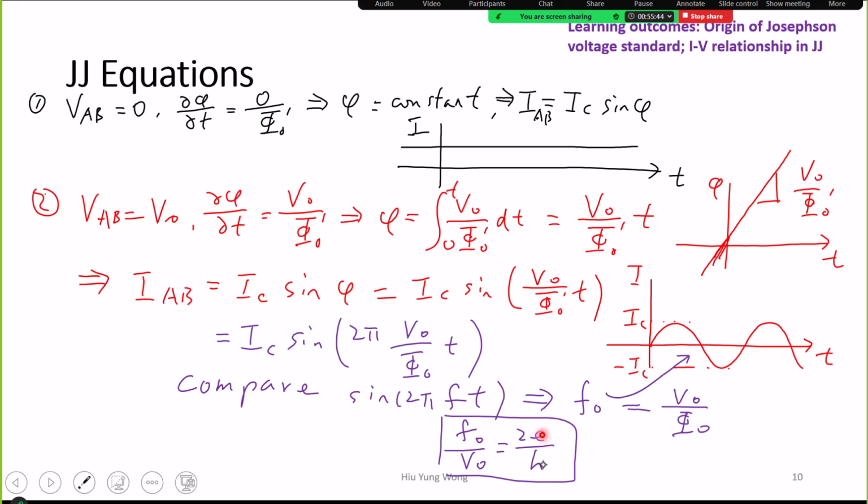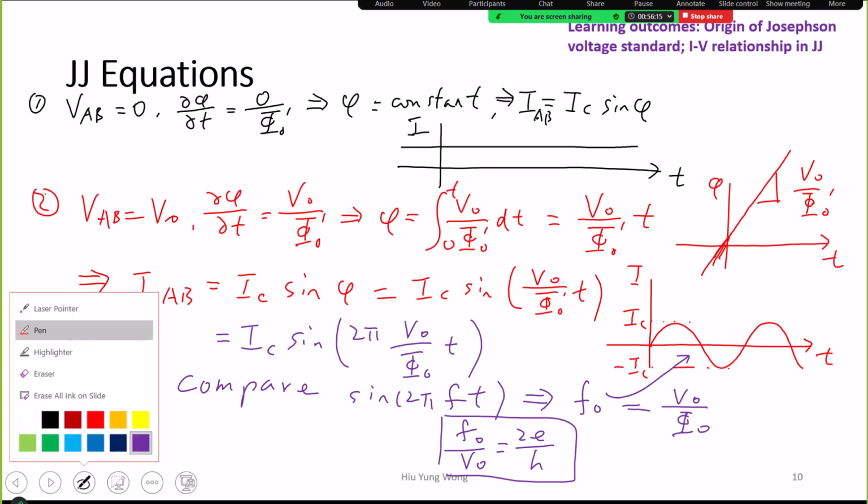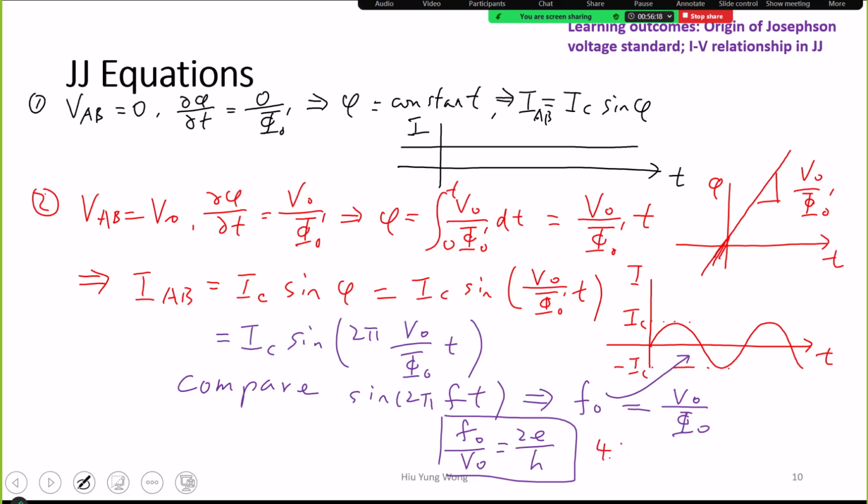And then you also know the electron charge and the Planck constant; e and h are invariant throughout the universe, constant. So I can define my volt. All I need to do is this experiment: fabricate a Josephson junction, although it might be different from the other one in South America. But when we do the measurement, we apply a voltage and try to get a certain frequency. And this is given by 4.83 times 10 to the power 14 hertz per volt.